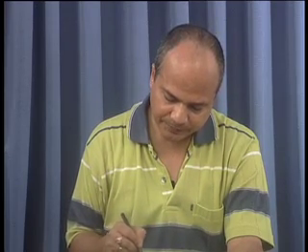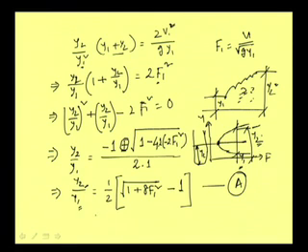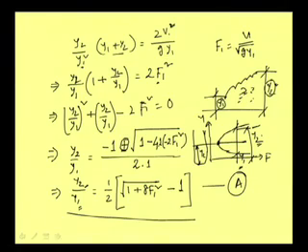Okay. With this very introduction to the equation of the hydraulic jump, here we should remember one point: this equation we are writing is very popular, but it is for a rectangular channel. If it is not a rectangular channel, rather a trapezoidal channel, then we cannot have our equation in this form. Then we will have to derive the relationship between y1 and y2 for the trapezoidal section.